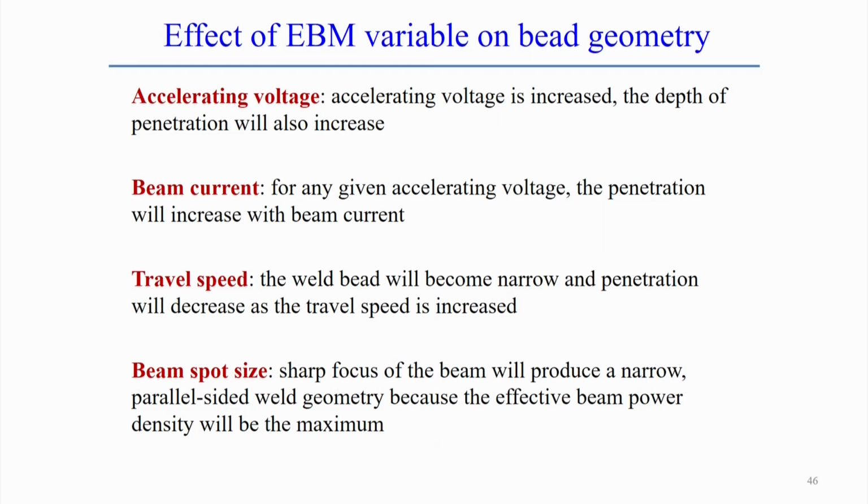Next is the travel speed. Basically, understand that if the travel speed is more, the amount of heat input to the workpiece surface actually decreases.